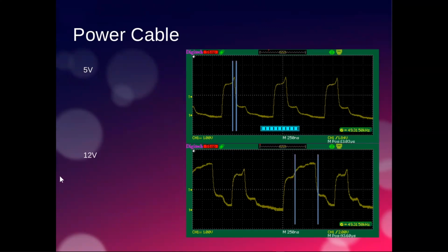The one here on the 12 volts, and this is much more likely to be accurate, you can see that it's wider, but it's a long way away from when the signal actually started to rise before it actually detects the rising edge. And if this had been much later, this 1 would probably have been read as a 0, right? And of course, that can lead to flickering.